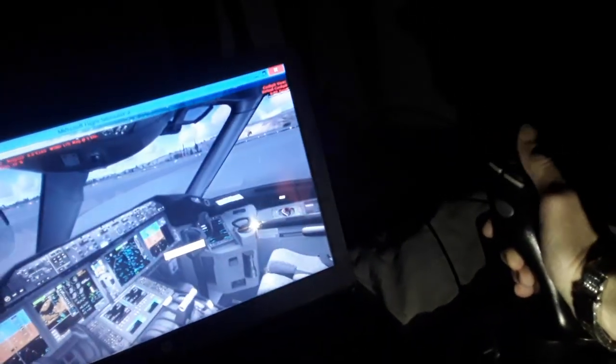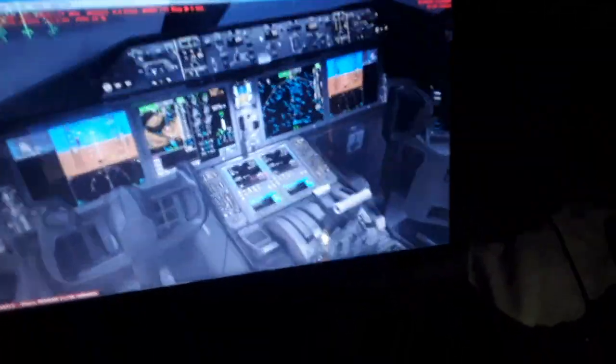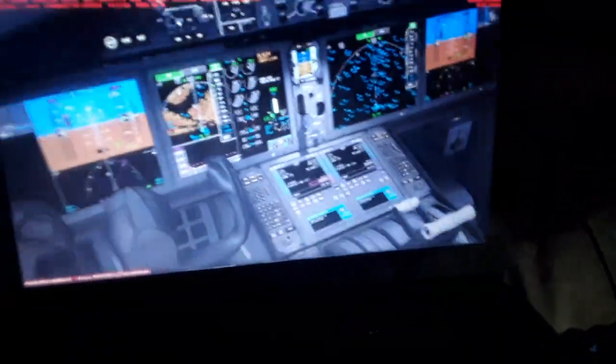So you can see the flight controls. I'll show you right now. So we have the flight management computer over here. I'm gonna create a flight plan. So I use the takeoff gross weight of the aircraft for this flight. As I told you, the flaps for takeoff 15 degrees. We're gonna use the mean aerodynamic chord position is gonna be 23% of the MAC using the fuel on board. The takeoff gross weight is gonna calculate the center of gravity using the left and right wings, fuel tanks, the center tank, and load compartments, the cargo load all over the aircraft, and the passengers.